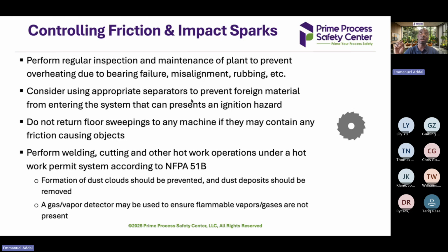And sometimes, I think I also investigated an incident in a dust collector where they have a central vacuum system and a dust collector, and they use the vacuum system to just take any dust from the floor, and during sucking, they sucked something, a metal, which went into the system and served as a source of ignition.